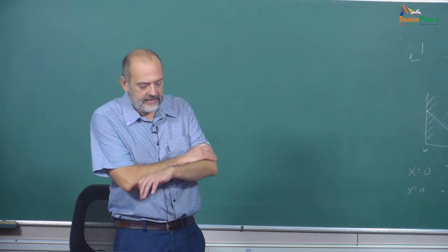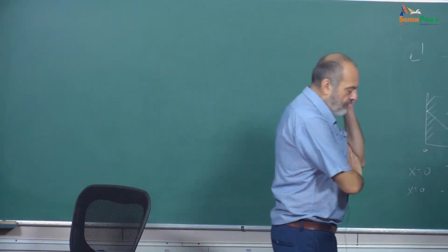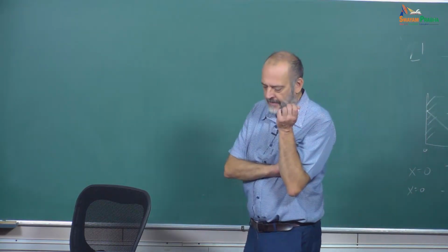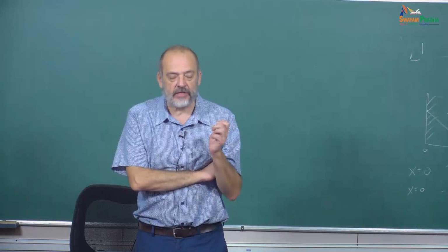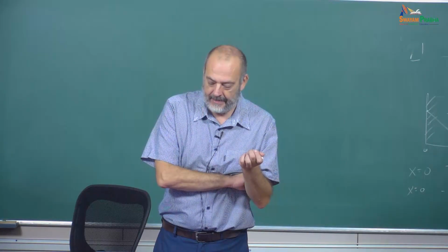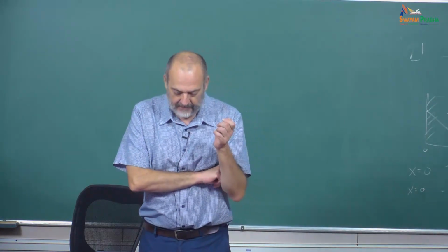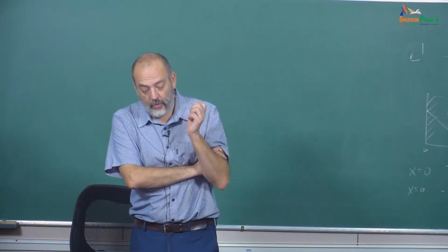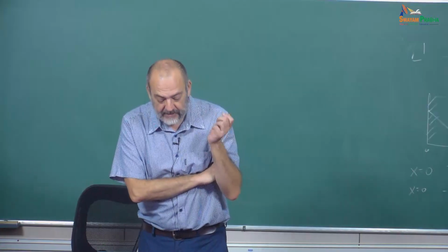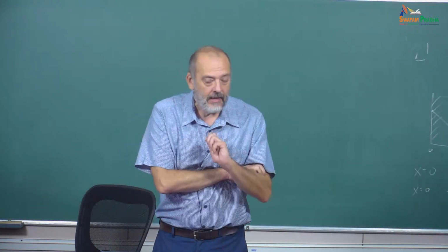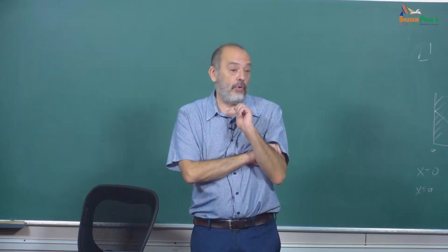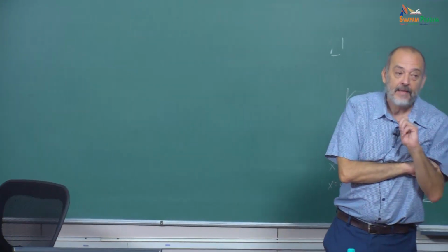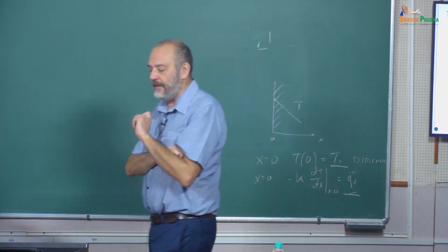And in this case, instead of the equation for the shear stresses, tau equals minus the dynamic viscosity multiplied by the derivative of the velocity in space, we have here the heat flux, and so we can write an expression that is finally defining what we have in the Newton law. In the Newton law, we have this H, but nobody knows exactly what it is. Now we have a little bit more information.